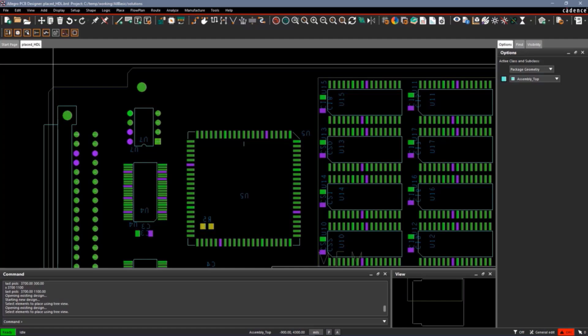This master design file will have items like the board outline placed, cross-section defined, some design rules set, maybe even some common components such as connectors already placed. Then this master design file can be used as a starting point over and over again. If you use this method, you probably will save yourself time and also ensure the accuracy of all your designs.